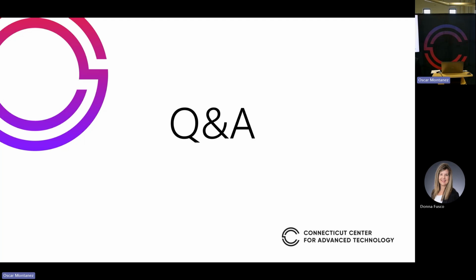Yes. Yeah, John, it's a really good point. So the NX Virtual Machine would still use the VCP file from your TRAK machine tool. The only difference is instead of having a CAD CAM system separate from your virtual machine, you would have one instance of NX where you take care of your modeling, your CAM tool pathing, and your simulation with that TRAK-based VCP file. If that makes sense. Thank you.